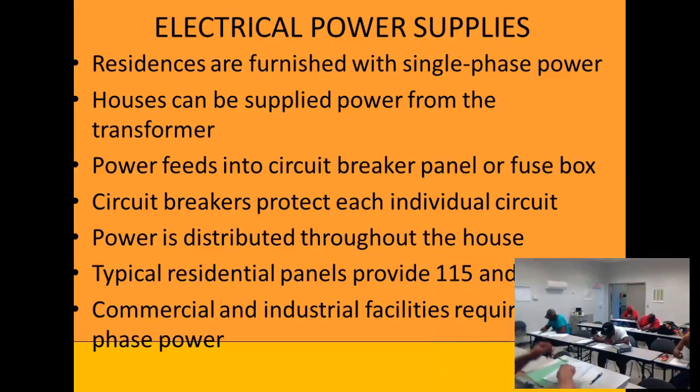Okay, so how does that affect us? If I have a piece of equipment that is rated for 230 volts and it's single phase, that means they're saying this thing is going to work if the voltage is 10% high or 10% low. So 10% of 230 is 23, right? So if I check with my meters, if I have a problem, one of the first things I want to look at is the voltage.